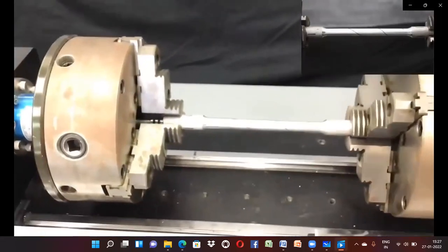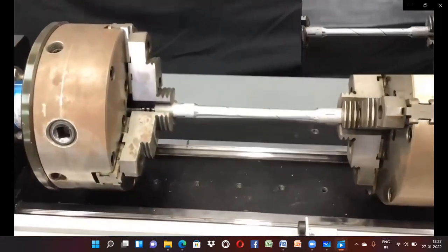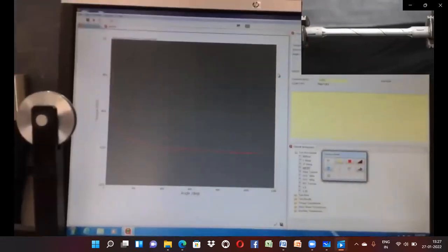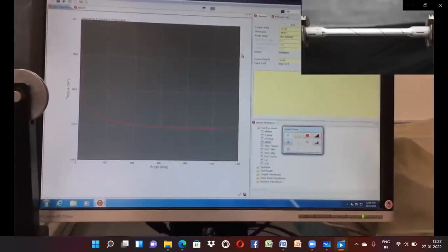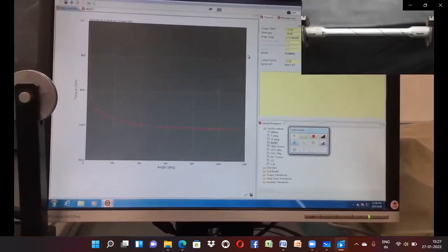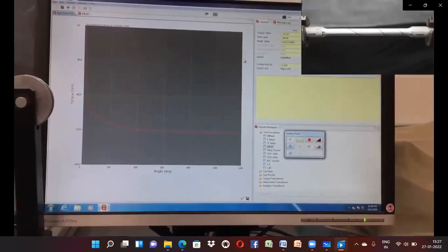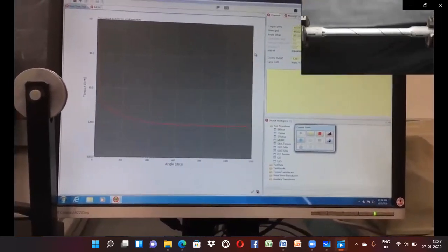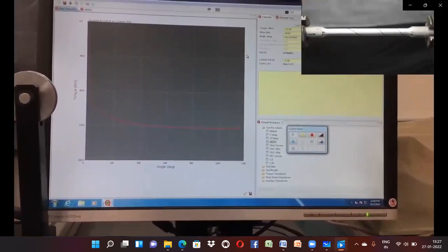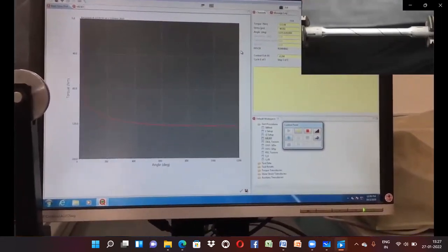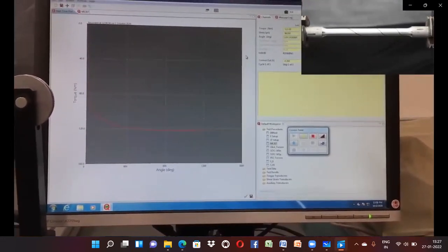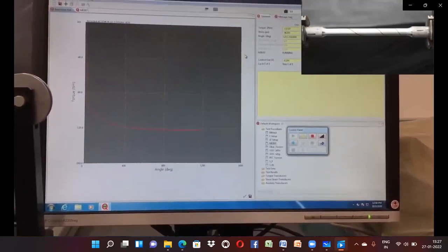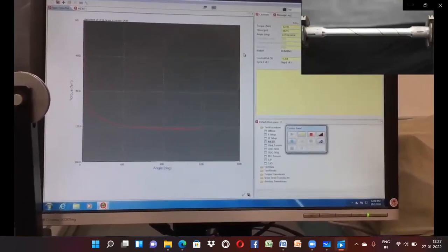And now we can see the shear stress, or the deformation, the angle of twist, appears to be maybe not quite as evenly distributed anymore. It looks like the lines on the right end of the specimen in the upper right corner there are kind of bunched up. If this was a perfect world, the angle of twist would be evenly distributed. But the fact that now it's definitely bunching up on the right end, you can see that the two right lines are very close together. So it's twisting more on the right end.